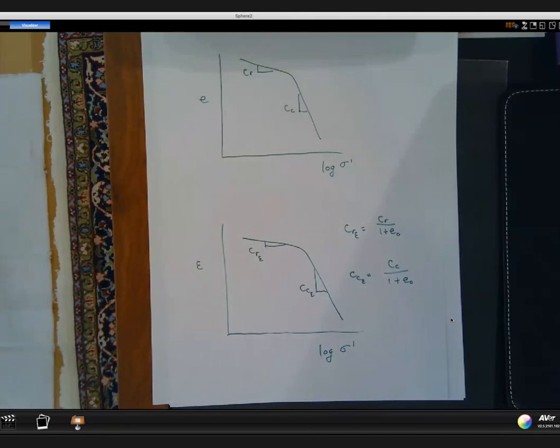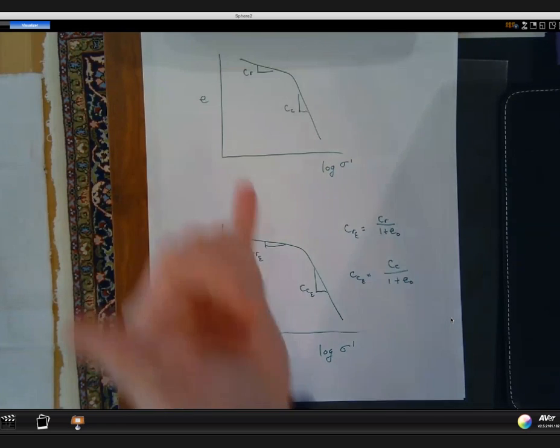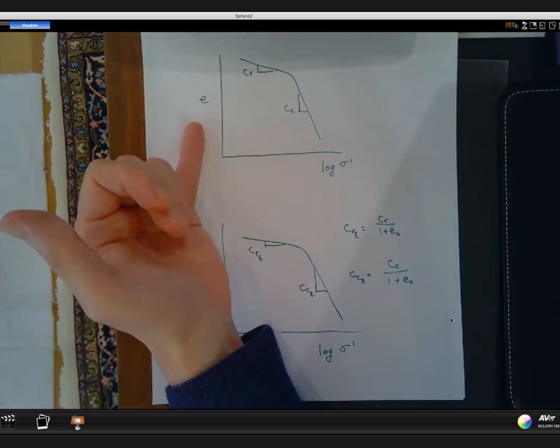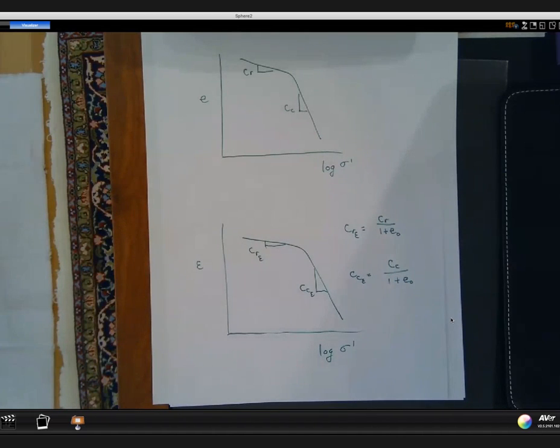And if a soil is going to start at an oddball void ratio, like a 2.8 or something, you know, an organic silt or something, or heading into a peat, which might have, you know, void ratios of 6 or 8 for a starting void ratio, knowing that number at the onset does help and provide some context for the problem.